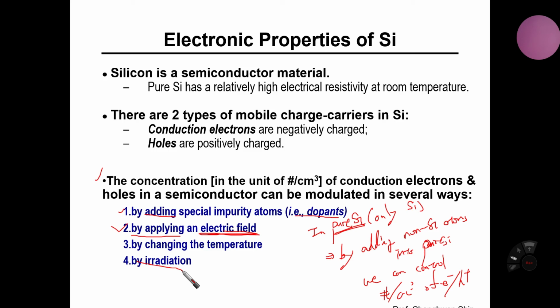The transistor has an MOS system, and the MOS system is a basic part of NAND flash memory. For cache memory or SRAM, more than 75% of the chip area of Intel and AMD CPUs is filled up with SRAM arrays. SRAM consists of 6 or 8 transistors for a single data bit cell.